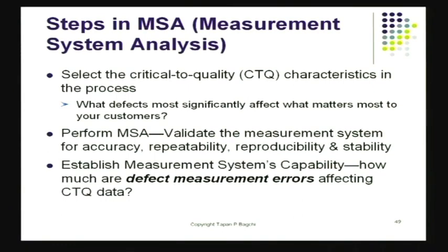we've also got to make sure that I establish the capability of this measurement system. It by itself should not introduce so many errors that when you try to measure parts per million, those figures are wrong. It should not be like that. So it's a very important step. In fact, before you go into your improvement step, before you start making measurements and so on, you make sure that the measurement system that you're applying to produce data out of the process is worthwhile looking at.